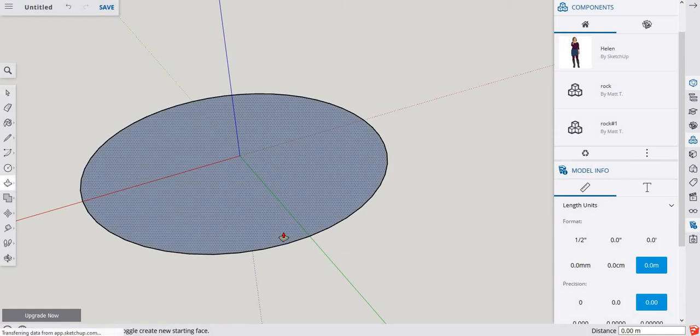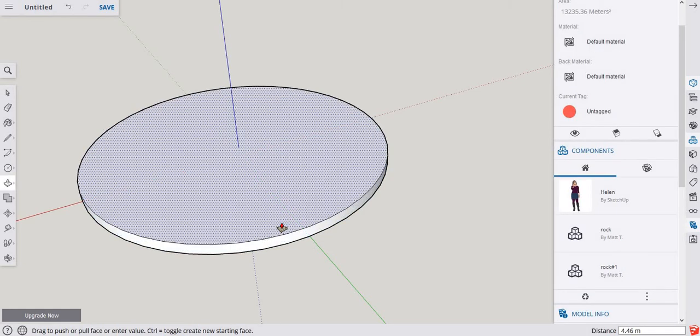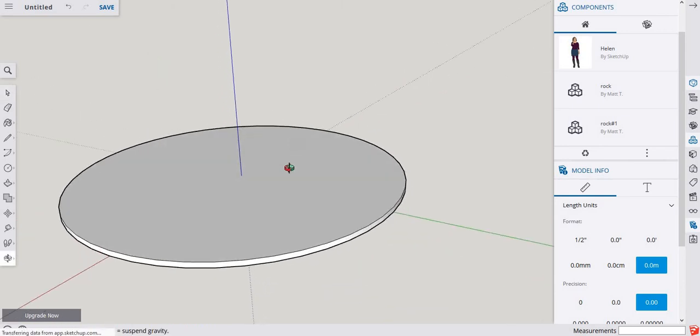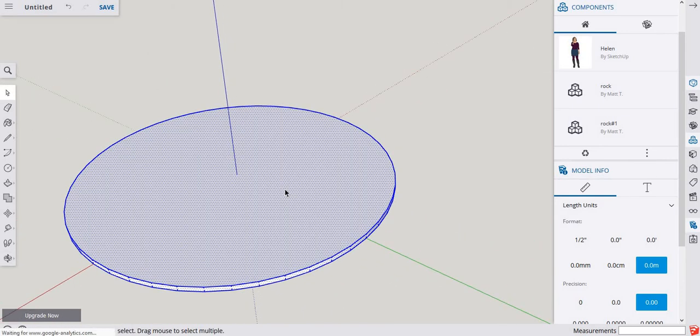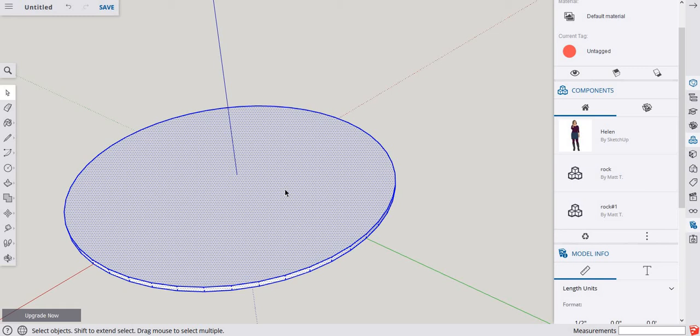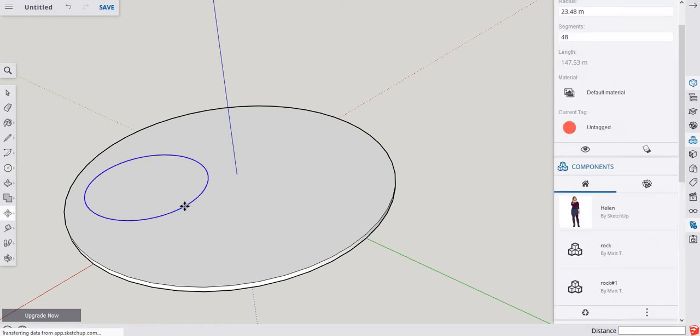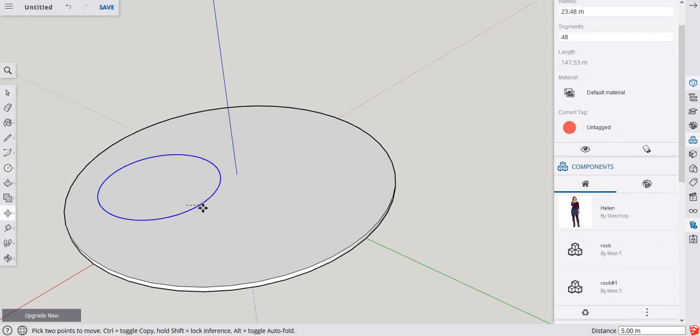Let's extrude by 2 with the push-pull tool, which is P. Okay, anytime I make a model, let's talk about when geometry gets mixed. So right now it's not a group. So groups or components are extremely important, because now if I draw on this face, and then I take this and hit M, and I start moving it, it moves.